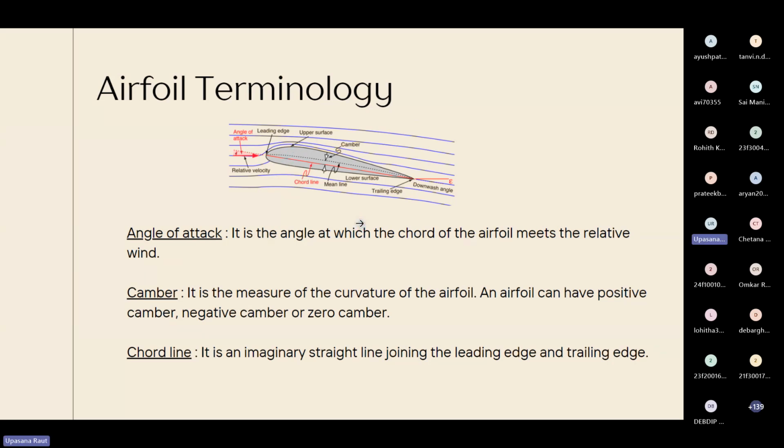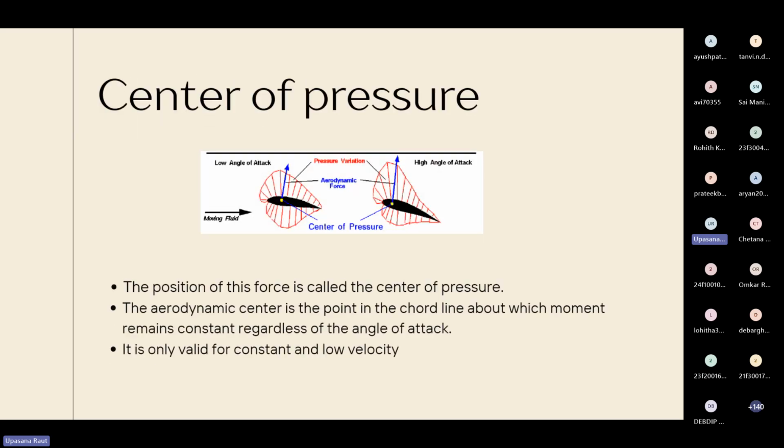And if the velocity is supersonic, which is higher than the speed of sound, again in general, the center of pressure would be halfway along the chord line. But I'm just giving it as information. It is always better to calculate it the way I said: find the resultant force and find the position of the resultant force. That position is the center of pressure.